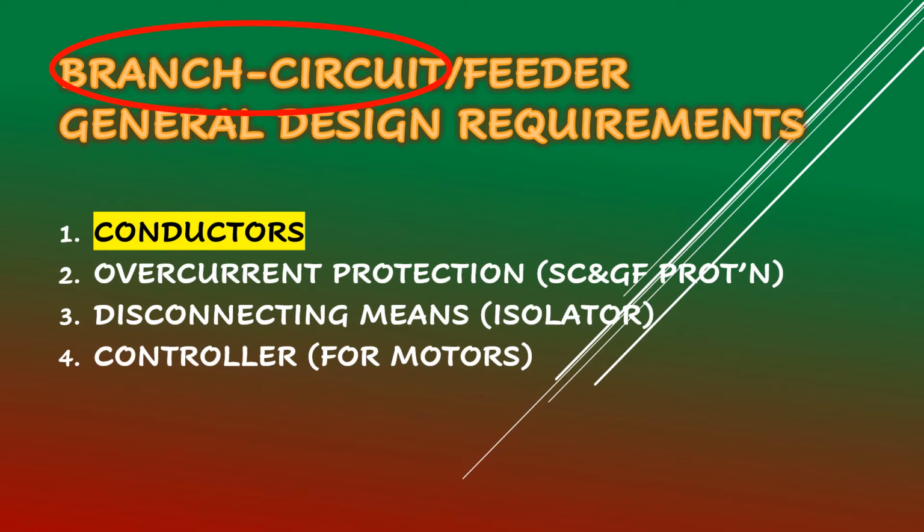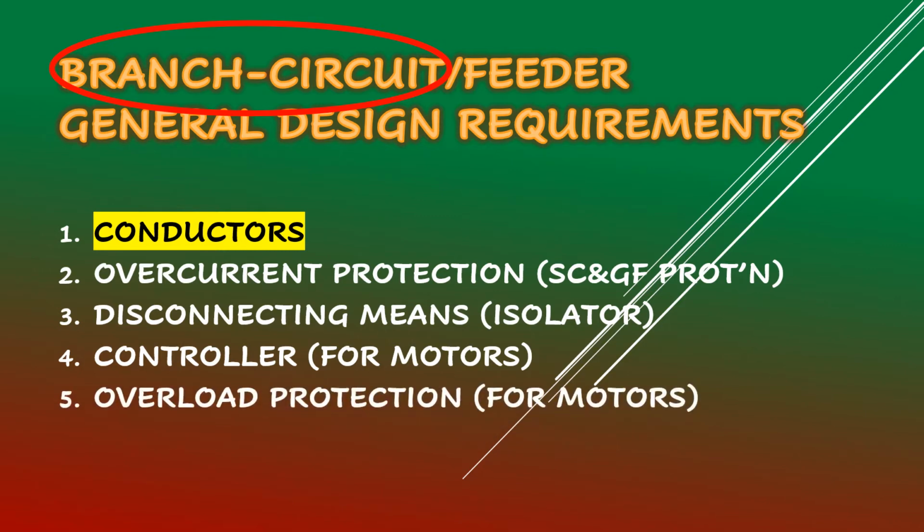Number four, we have to consider the controller, if the load is a motor. And number five, we need to design the overload protection. This is again mostly for motor loads. Now let us see how the motor feeder and branch circuit look, so we will have a clear understanding of what we are going to do in each of these components of the circuit.